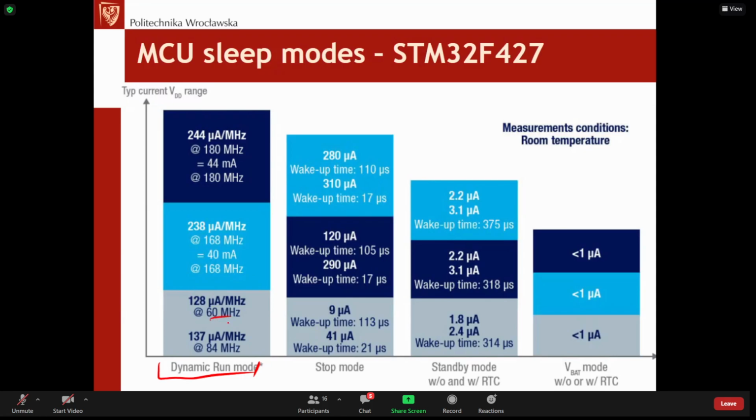This one is about 100 MIPS, this microcontroller about 200, and this about 250 Dhrystone MIPS, because it's a 32-bit microcontroller. They have power consumption here not 2, 3, 4 milliamps, unfortunately, but closer to 40 milliamps, so about 100 milliwatts. That's already quite a substantial value, especially compared to the 8-bit microcontroller analyzed a moment ago. So the 32-bit, unfortunately, is not that effective.